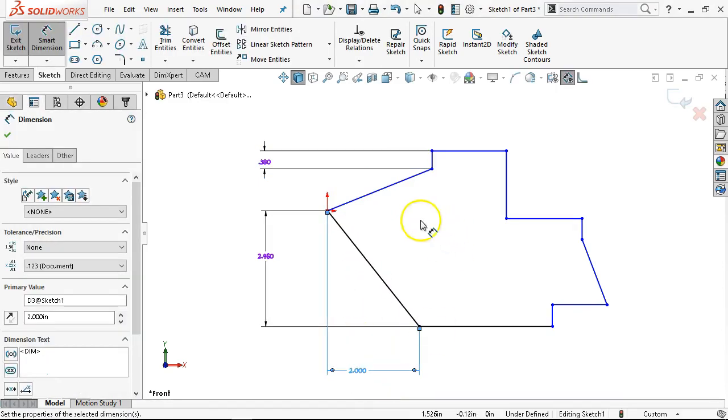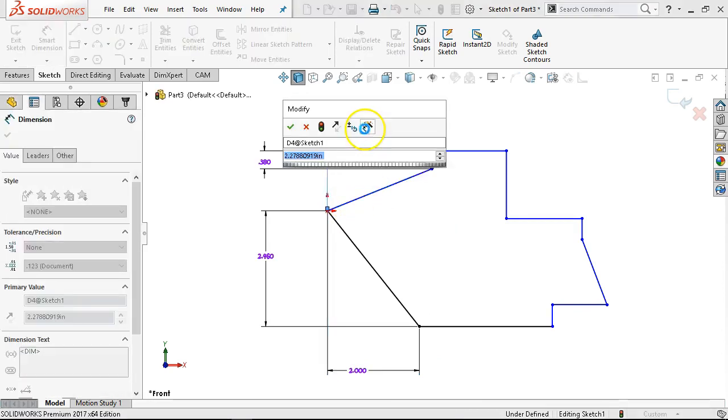And it's easy for me to say, but until you see it and experience it, I've had like 9/32, 0.28125. That fifth decimal place has bitten me when I've had enough elements or enough objects stacked up, and it added up to put me out of my desired tolerance by 10 or 15 thousandths.